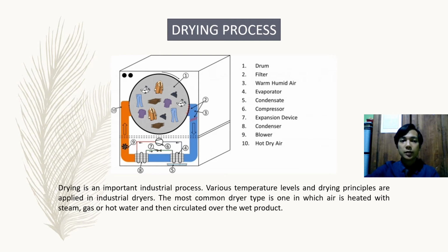Okay, so the standard procedure is to exhaust this humid air or dehumidify it. With a heat pump, heat can be extracted from the humid air, and then the air is cooled down and dehumidified. The extracted heat can be increased in temperature and used to heat the dryer. Thus, the use of a heat pump serves two purposes: heating the dryer, and dehumidifying and recirculating air. Heat pump assisted drying can give high efficiencies because of this.